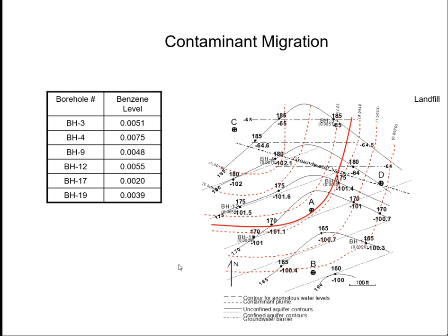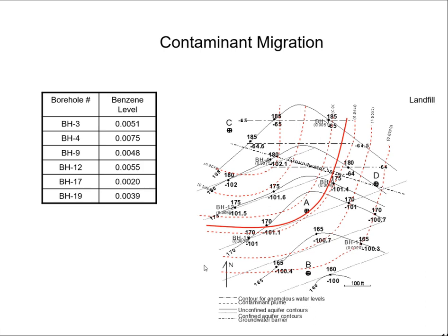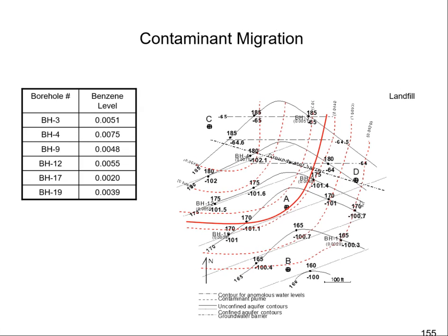And so the question that it's asking here is, where are we going to drill next to determine the lateral extent of the contaminants? To me, lateral extent means everything out in a generally horizontal direction from the source. So the way I've drawn this, I would select B because it's beyond the last contour that I put here for the lowest level of contamination.